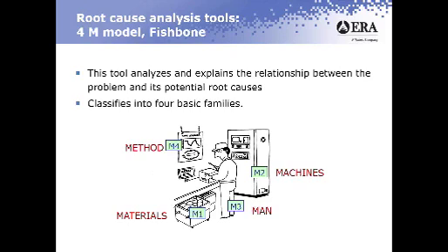Okay, the other tool, which is actually one of my favorites. All these seem very simple, but this is one of my favorite tools to use. Sometimes the 5 whys work better. Many times the Fishbone will cover it as well. But basically the 4M model, Fishbone, Ishikawa, also it could be the 4P model. There have been many names for the Fishbone.